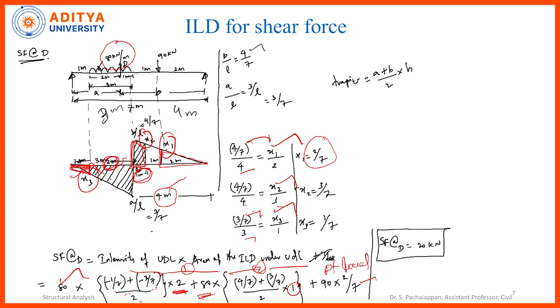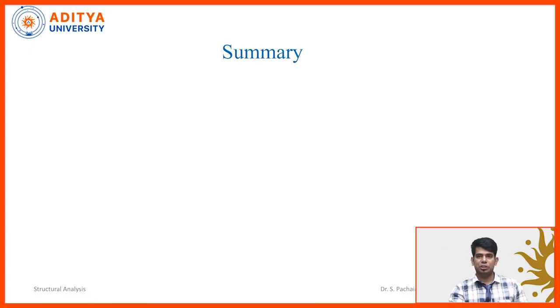If it is a point load, then point load multiplied by the corresponding ordinate. If it is a UDL, then the UDL multiplied by the shaded area of the ILD diagram under the UDL. In that case, we can calculate the shear force.